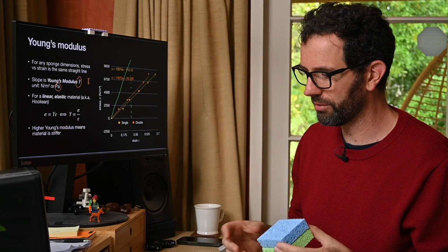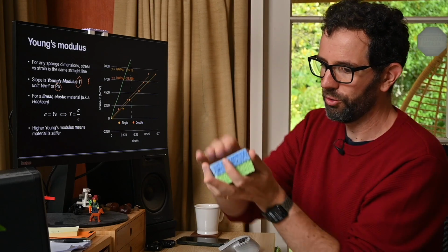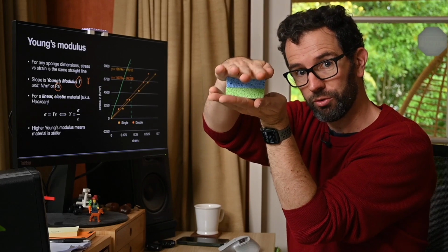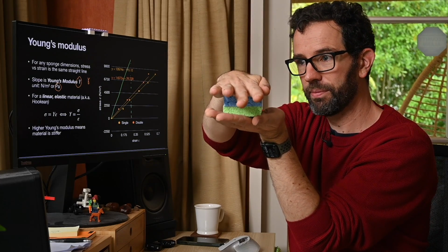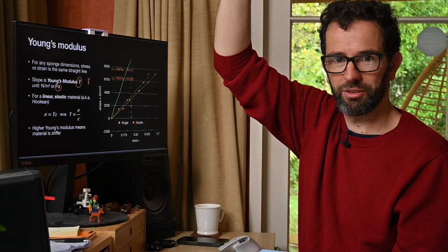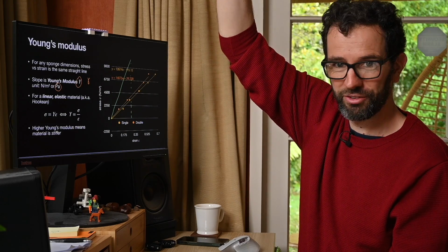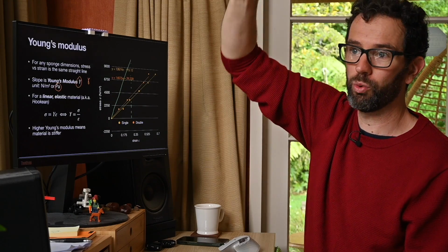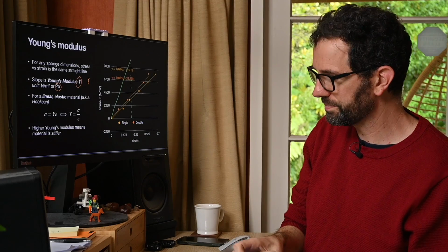Okay, maybe a helpful way of remembering how some of this works is we discovered with this experiment that the same force compressed more in absolute terms, but the same strain. So I kind of think of the princess on the stack of 20 mattresses. If you put a mass on a very tall object made of your substance, it will compress quite a lot, but the strain is the same.